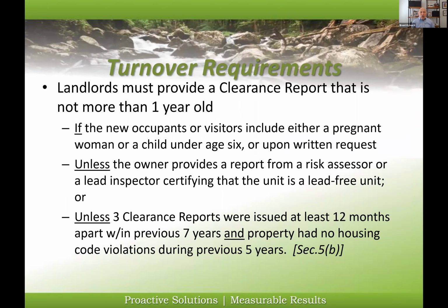All right. Turnover requirements in DC. Turnover requirements are this. Anytime an apartment or a rental unit is turned over in the District of Columbia, a clearance report must be provided to the new tenant that's less than 12 months old. And the clearance report involves lead dust wipe testing throughout the unit. There needs to be testing in every room of the unit.